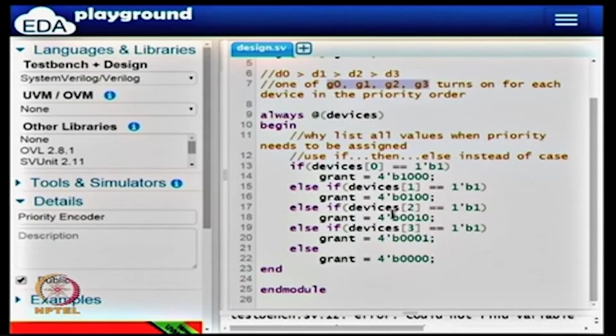This is using an always block, the previous one also used an always block. However, even within the always block, which kind of statement you pick, there is beauty in the code here. This is much more natural, and in terms of hardware, this is much easier to translate, and this is less error prone, because this explicitly says these are the bits I am looking at, and that is all. If you are to type even, let us say, 2 power 6 lines, somewhere you may make a mistake, so that will not happen here. So this is a very nice style for writing this priority encoder.